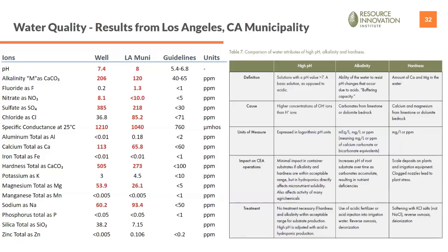The alkalinity has reduced a little bit, but chloride level is higher, most likely because they're adding bleach or chlorine to the water to disinfect it for drinking water. And that's also a component that you'll want to take out of the water before irrigating your plants, and certainly if you're going to cycle it up.